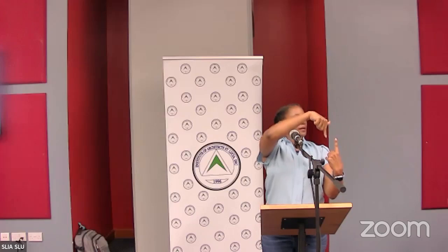So for a column, for example, this might be the center of my column, but instead of the load coming down directly through the center, I can have the load acting somewhere to the side of that center, which means I'm also inducing what we call a moment. So it can also cause the column, with that induced moment, to kind of rotate or turn. So it might bend about that axis. So it has to be designed for any load on it to be transmitted in that way.